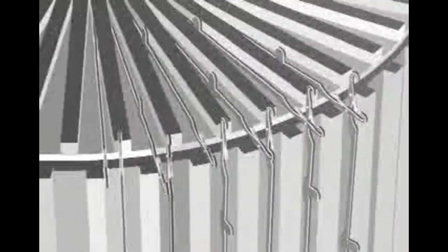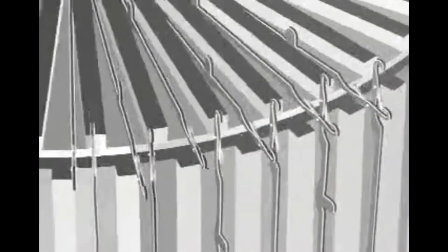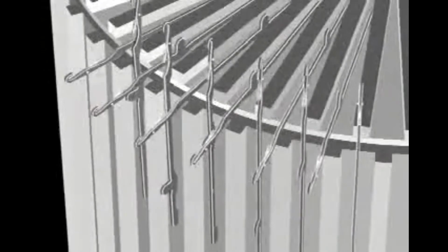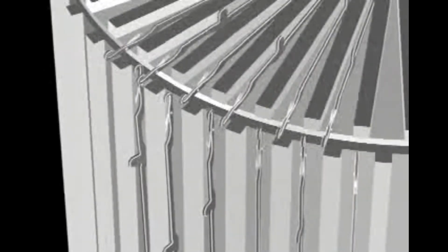With rib gating, the two sets of needles are not directly opposite each other. The needles of the cylinder are between the needles of the dial. Here you can see how both sets of needles can knit at the same time without touching or hitting each other. Although all needles have the same length, the butts are in two different locations, which activates the needles to create patterning.